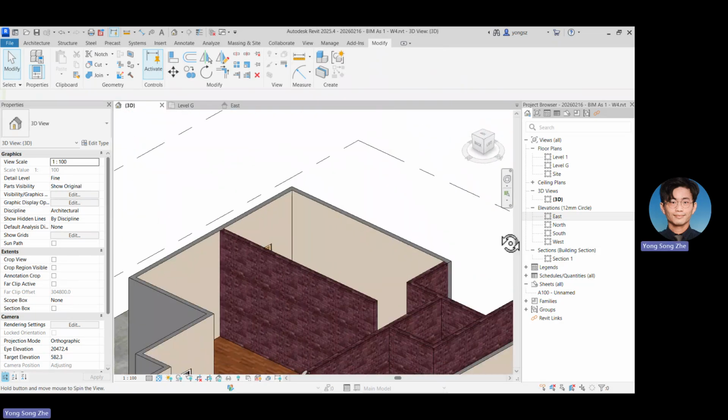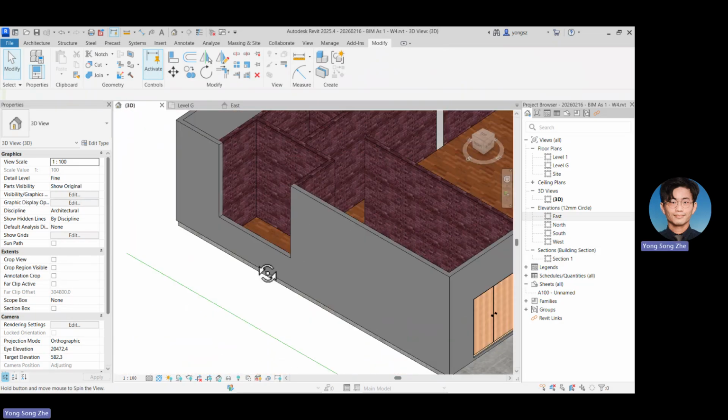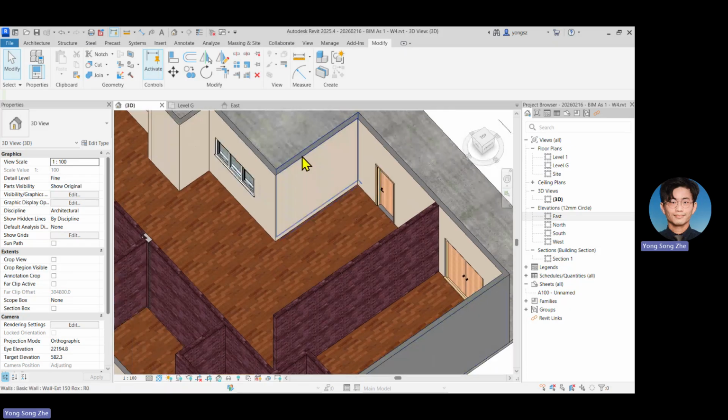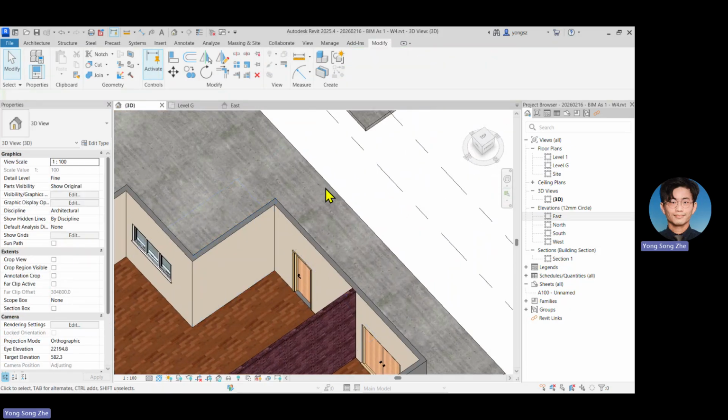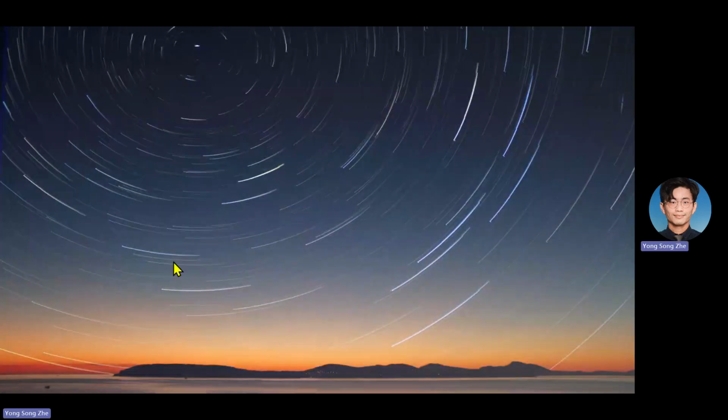Okay, now the interior, you get these finishes, this color, render beige smooth. Maybe on some of the walls it is the wrong way round. So can you switch it? The answer is yes. You can select the wall and hit the space button. Let's try now.